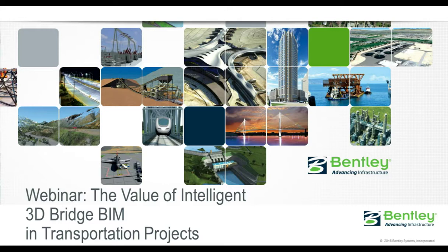Thank you, Bob. And again, thank you for attending this webinar. One of the first things that I wanted to mention to you is interoperability. This is a powerful word. How can we take one model and relate to civil data, so that when we change alignments, the model changes? What about the DTM? If you have it, can we use it to automatically calculate the top elevation of the footing, for example? It's powerful, right?